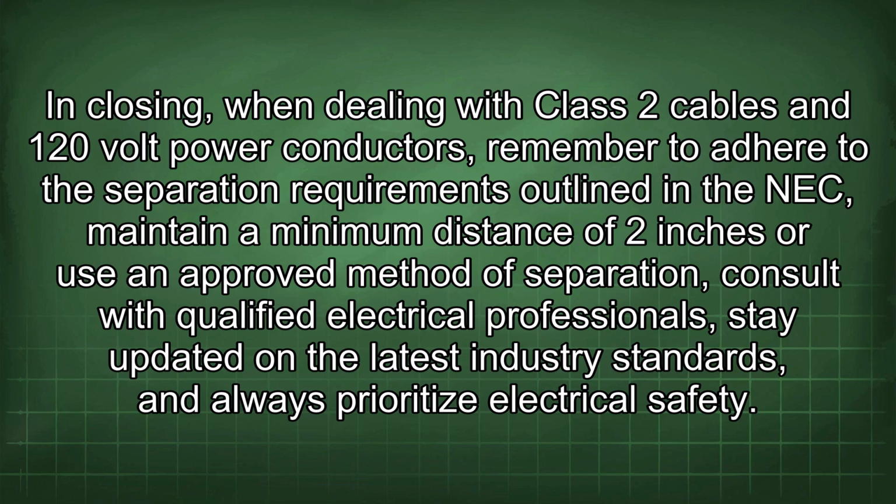In closing, when dealing with Class 2 cables and 120-volt power conductors, remember to adhere to the separation requirements outlined in the NEC, maintain a minimum distance of 2 inches or use an approved method of separation, consult with qualified electrical professionals, stay updated on the latest industry standards, and always prioritize electrical safety.